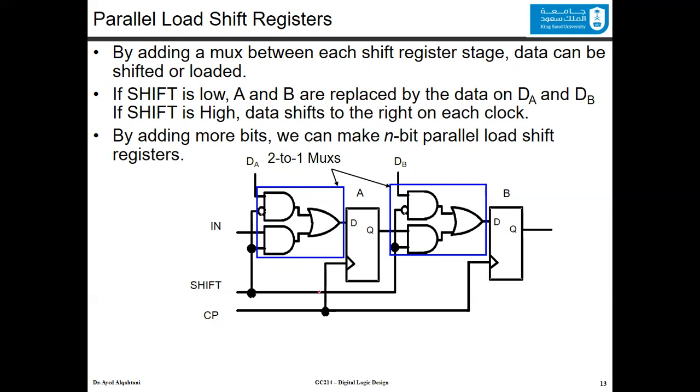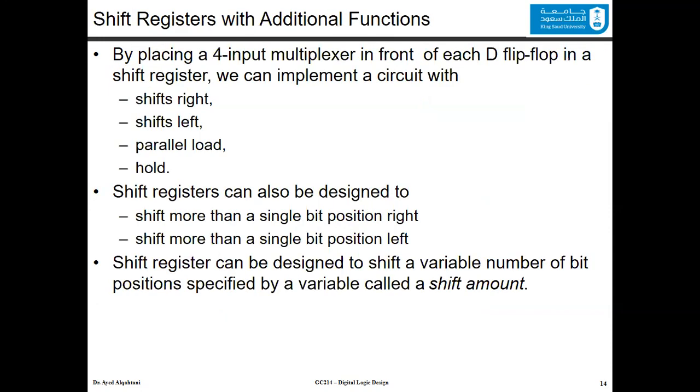The same idea in all of the types that we studied so far is that the clock is going to be inserted in both of the flip-flops here, meaning that at the rising edge, this flip-flop will pass the value inside, and this one will pass its value and store it inside. Now, there are shift registers with additional functions. We discussed some of them, like the loading and shifting to the right.